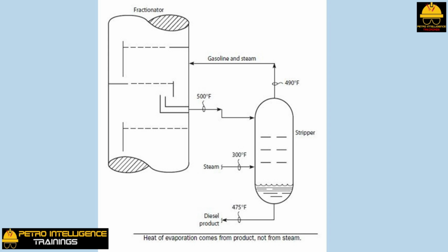If liquid drawn from a column is cooled below its bubble point as a result of ambient heat loss, we say it is subcooled. Mixing a small amount of steam with subcooled liquid will reduce the partial pressure of any vapor in contact with the liquid, but not enough to promote boiling. Eventually, as more and more steam is mixed with a subcooled liquid, it will begin to boil. But for a given amount of steam, the amount of vapor that can be boiled out of a liquid will always be less if the liquid is subcooled. In this way, ambient heat loss reduces the stripping efficiency of steam.